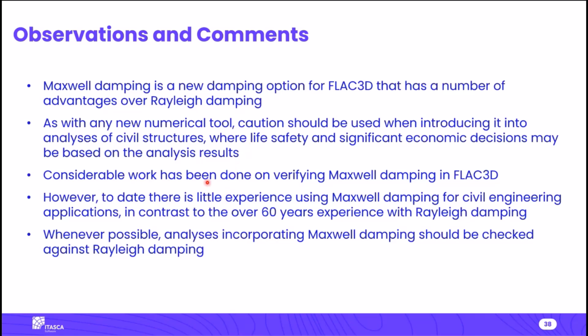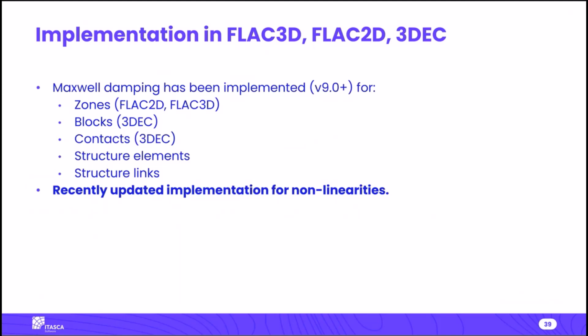We've done considerable work on verifying Maxwell damping in FLAC 3D, but to date there's been little experience using it in civil engineering applications. That's in contrast to Rayleigh damping, where we have maybe over 60 years of experience in seismic analyses. So whenever possible, you should spot check analyses incorporating Maxwell damping and benchmark them against Rayleigh damping analyses. So Joe, do you want to take over?